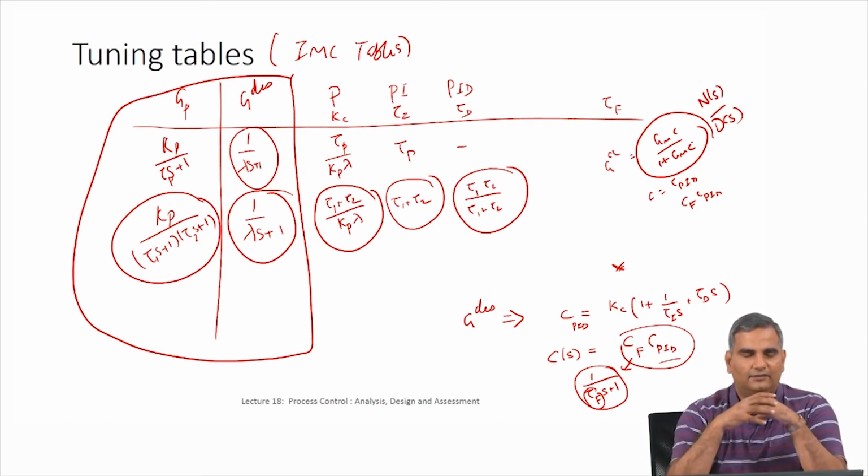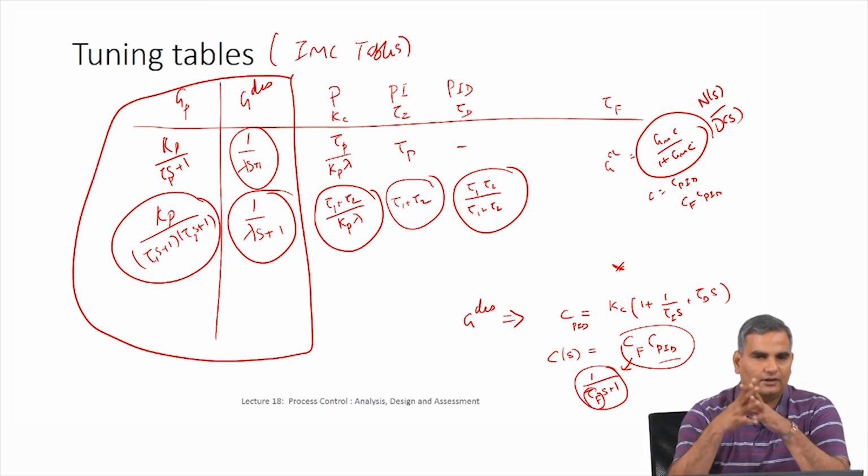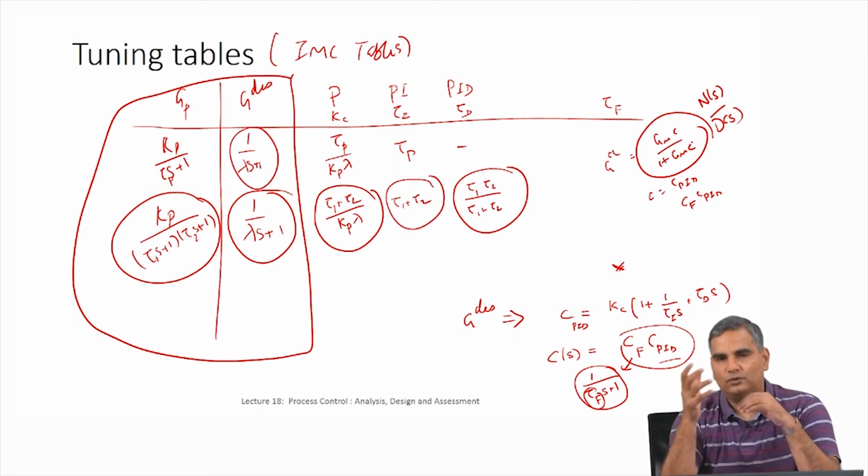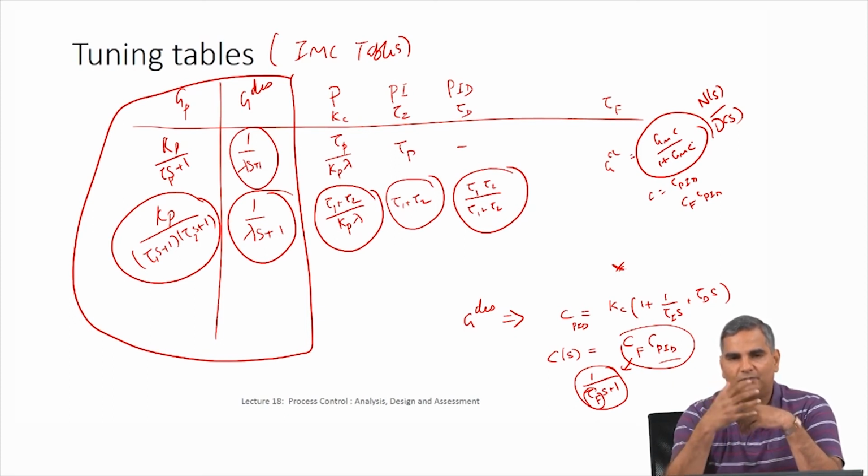So here I said if I have a denominator polynomial which has coefficients which are all constants, then you can actually get the roots and then understand stability. However, if I have these coefficients also as functions of the controller parameters, then we want to know what happens to the stability of the system, and without knowing the controller parameters we cannot actually get the roots. Okay. So we came up with this Routh stability table where remarkably you can actually make decisions about whether there are any roots in the right half plane without ever computing the roots.